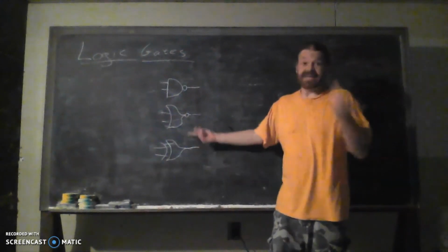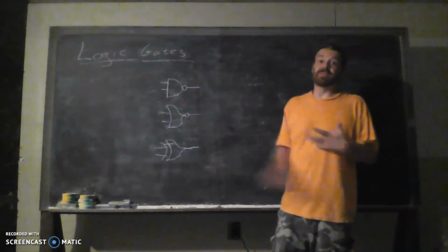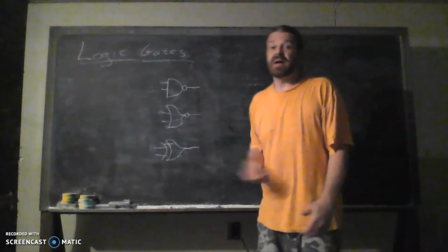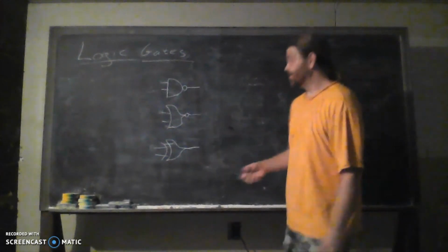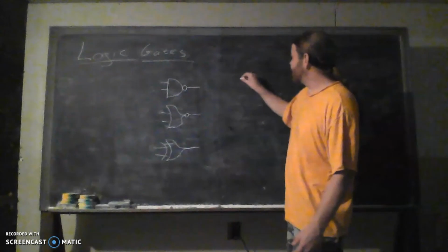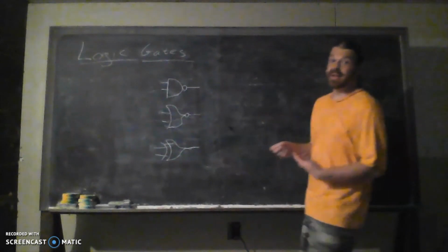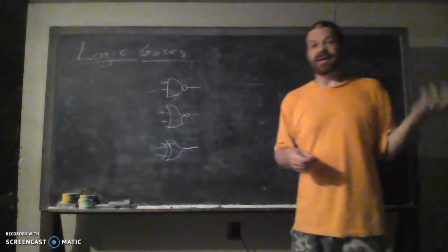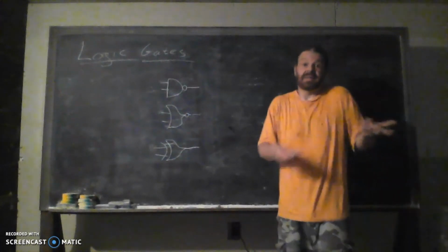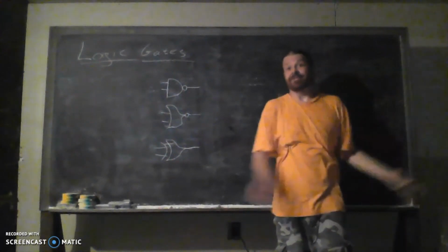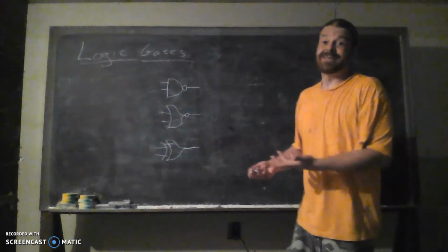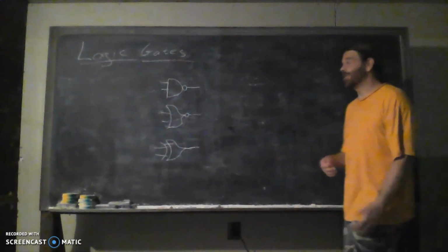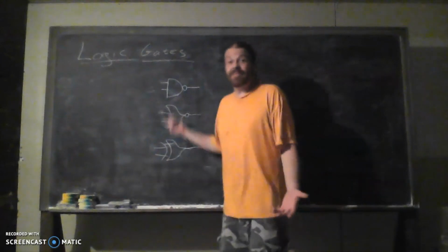And the reason I left it off is because even in the simplest form, we build it up from a not, an and, an OR. Actually, if you're curious how that works, we go through an OR gate and an AND gate both, and then the AND gate triggers an inverter, a not gate, to turn everything off. So if both lines are on, then the circuit gets turned off. So it's built up of the previous ones.